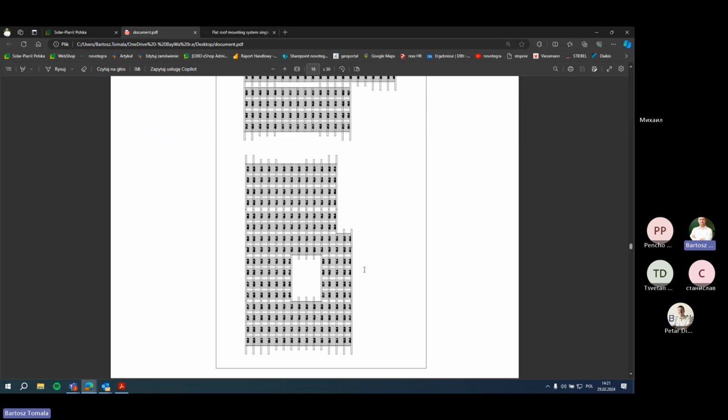In this case, it was 25 kilos per square meter. So our static engineer can recalculate the ballast and say that, for example, here, here, here, and here, you will have to put the welded plates, and it will allow us to stay below this value.